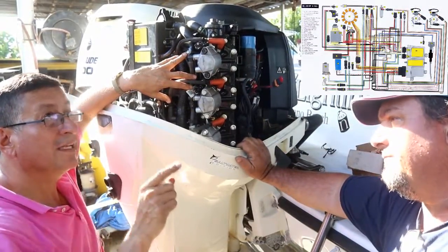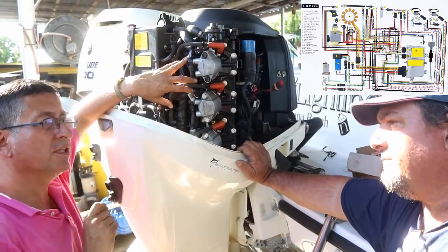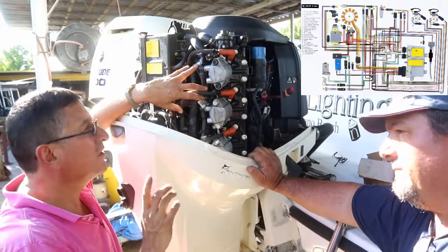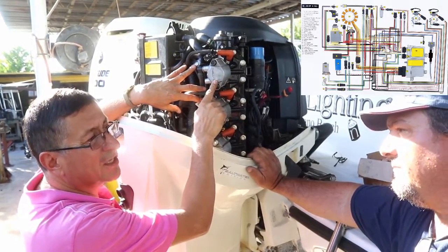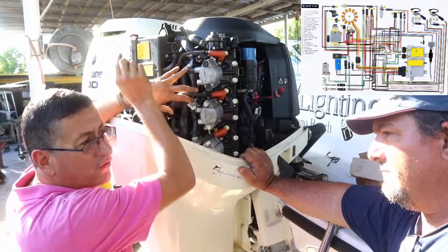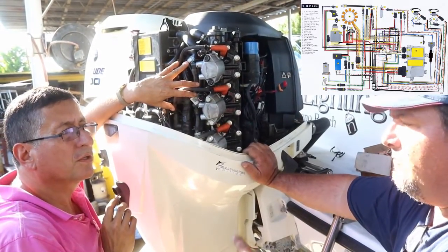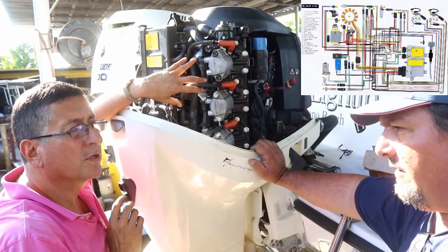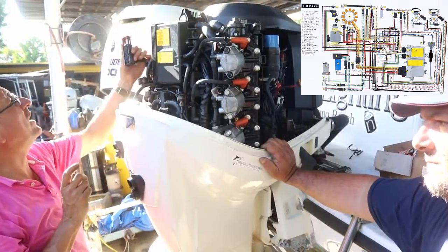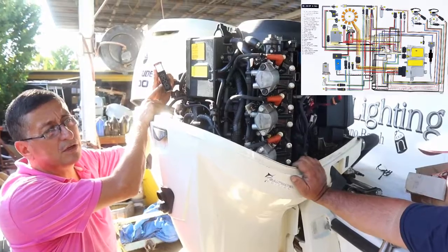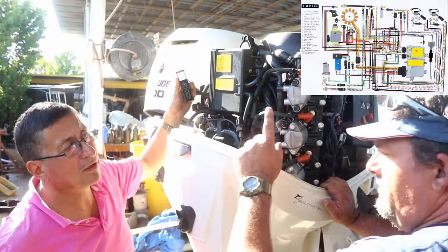For that reason, the diagram that we have on top at this moment is critical. Each pin of this injector is over there, so you need to follow the diagram. It's a simple procedure. I'll show you on the motor where it hooks up to the computer and where those pins are. You remove the harness here and verify the pins, checking continuity according to the diagram.